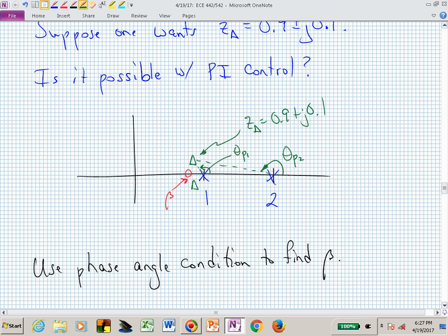To go from the real line to 0.1 is 0.1. So now the acute angle is 0.1 plus a vertical of 0.1. It's at 45 degrees. My obtuse angle, or the supplementary angle, is now 180 minus 45, or theta p1 was easy. That's 135 degrees. Is that clear?